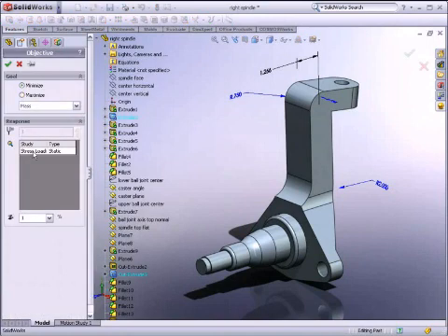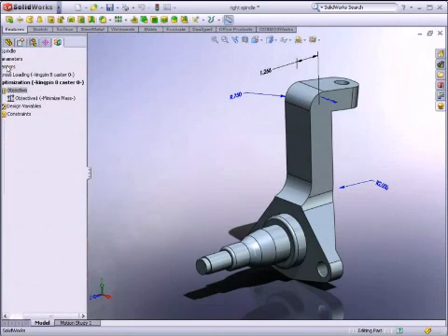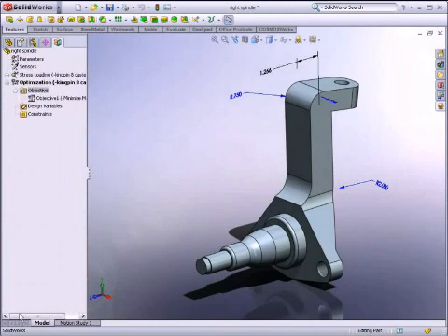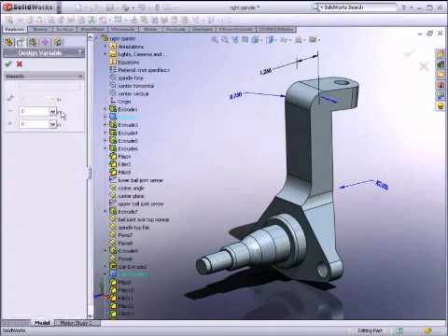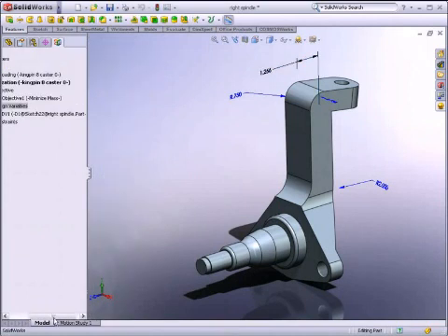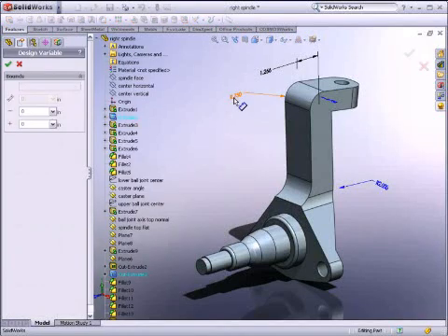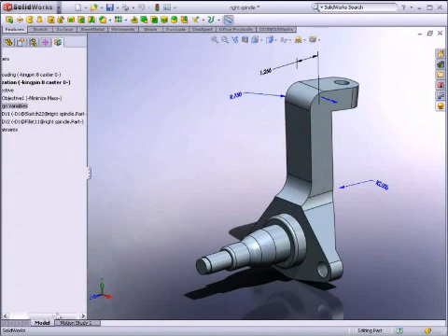First, you define the objective. This tells SolidWorks Simulation what must be minimized or maximized during the optimization process. You can base the objective on dimensions, mass, or volume. For this example, we will define the design variables by selecting dimensions in the model and specifying the boundary values.